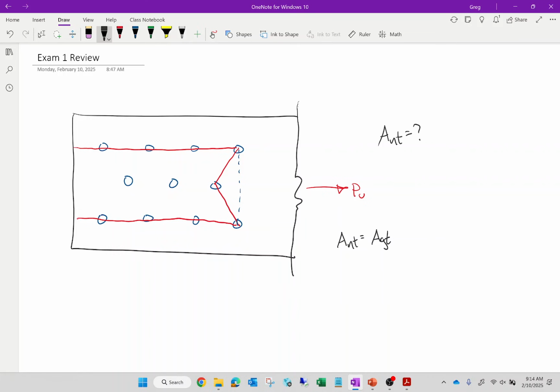And what I would do is I would say minus 2 bolt holes plus 2 stagger factors, where for this, just figure out what S is, figure out what G is. Now some of you might be thinking, wait, isn't it 3 bolt holes? Well, there's 1 bolt hole here, a half, and a half. That's why it's 2. But again, I'm not making y'all do that, so don't worry about it. The point is, it's just another problem. That's how I would do it.